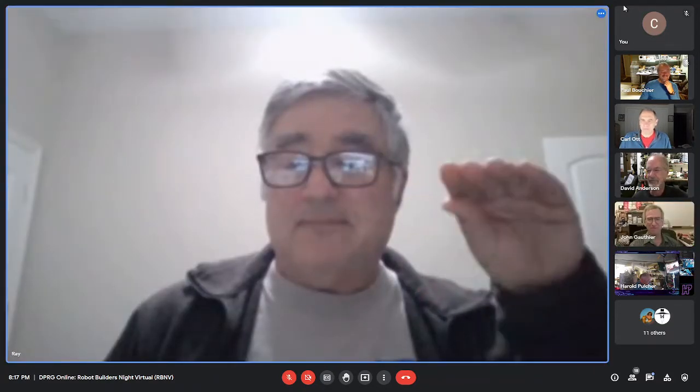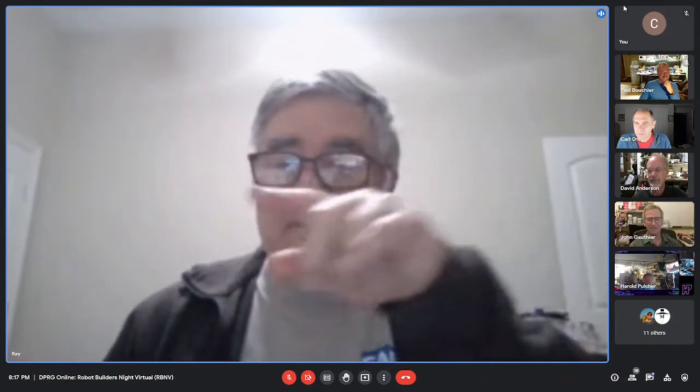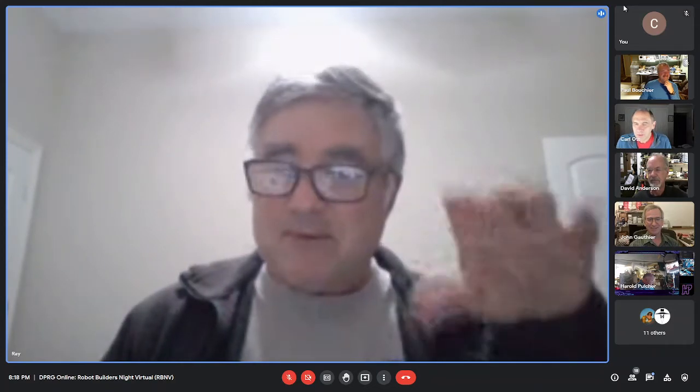David, I didn't use subsumption architecture for those 3 modes. It was a little too primitive for that. Well, it can always be improved. If you're talking slowly, saying something like, "Hey, you," that could be slow jaw motions. It's probably a matter of picking the right vocabulary. If I add enough behaviors and more actual inputs to control the behaviors, maybe I'll have to go to subsumption architecture. Or could you tie the jaw to a peak audio level and a servo, so that louder tones open the jaw more?